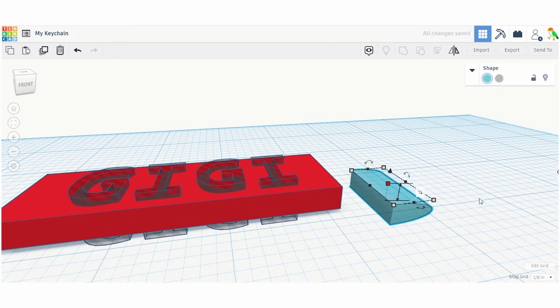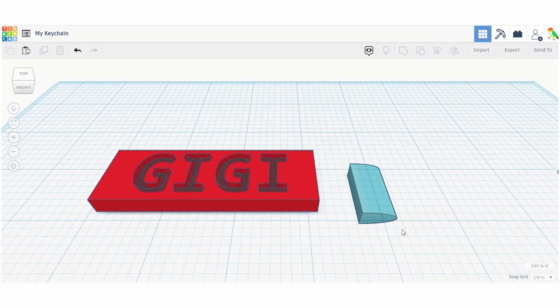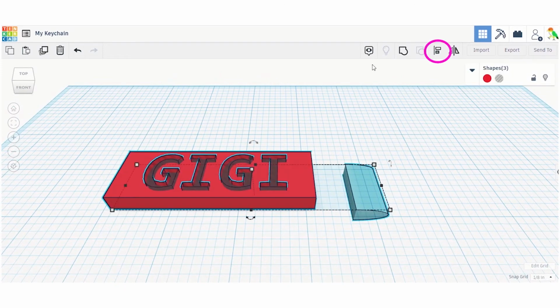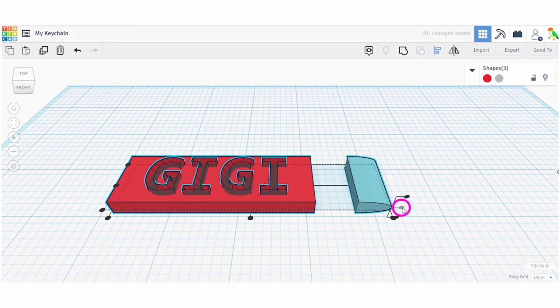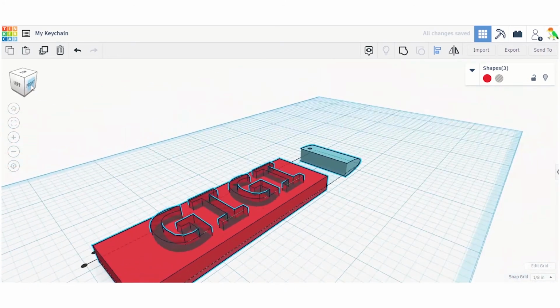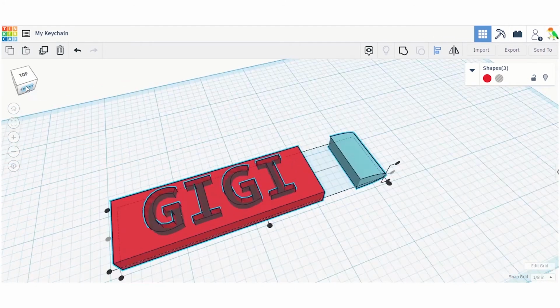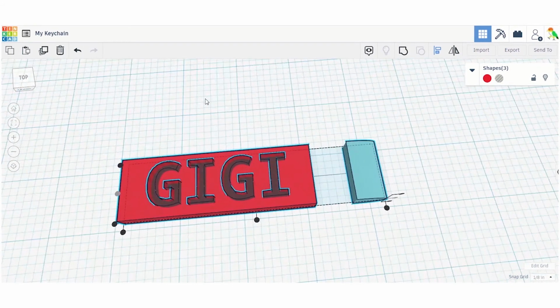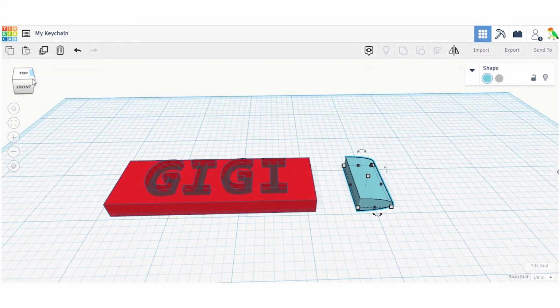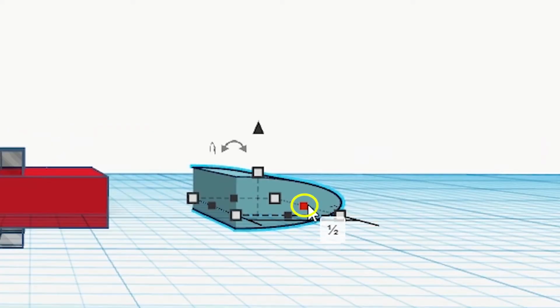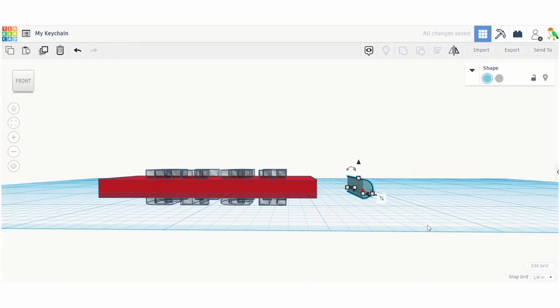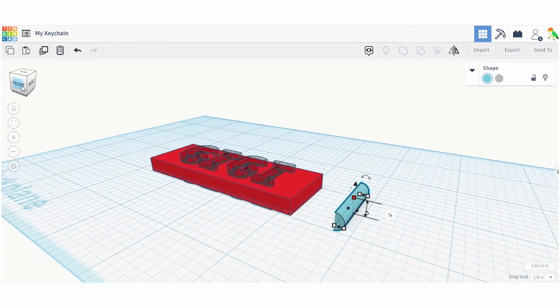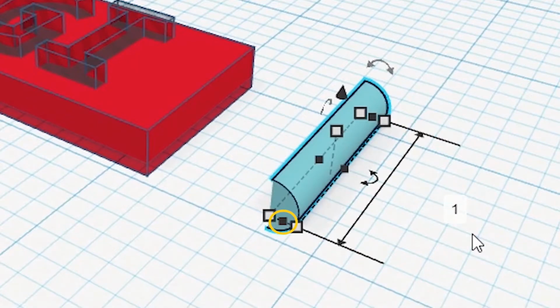Align the shapes to get a more accurate view. Select all shapes by drawing an invisible frame around them and click Align. The round node handles will appear. Select the center node along the vertical line of the round shape. Next, adjust the rounded height of the round shape to 0.125 inches and the vertical height to 1.0 inches.